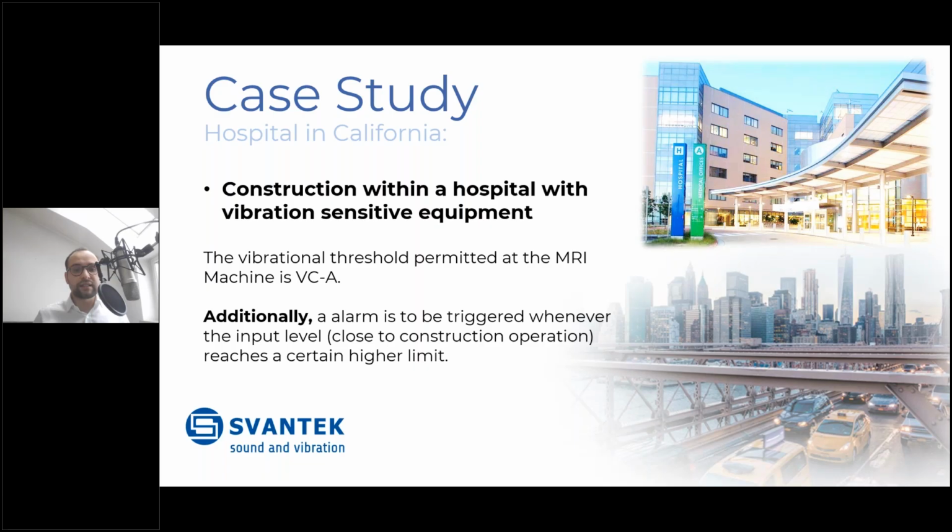Additionally, there is a requirement that an alarm should be triggered every time the input level, the level coming from outside the area where the MRI machine is, close to the vibration source, is higher than or equal to the level inside the MRI room. That way we can start looking at occurrences that were not triggered by a patient walking out of the MRI machine or a technician cleaning or servicing it, but whenever we have a higher level at the input of the vibration field than wherever the machine is.